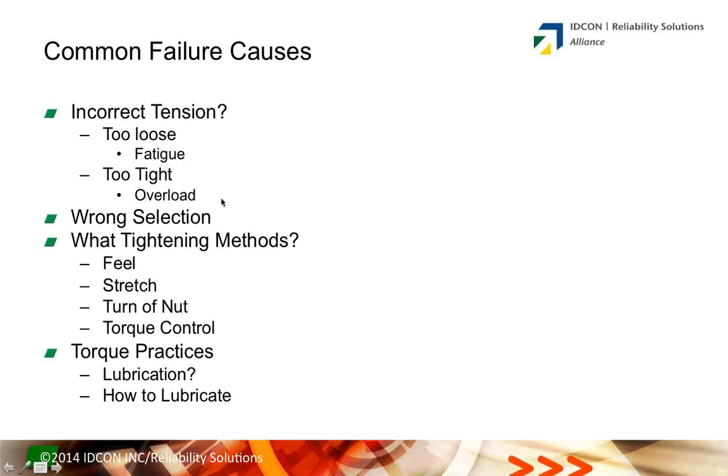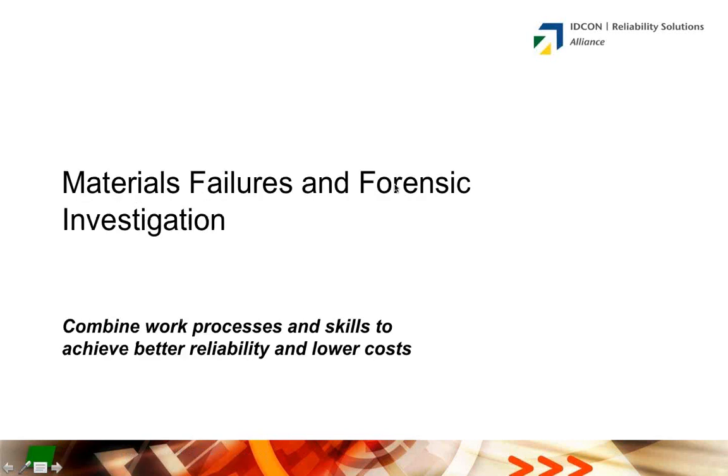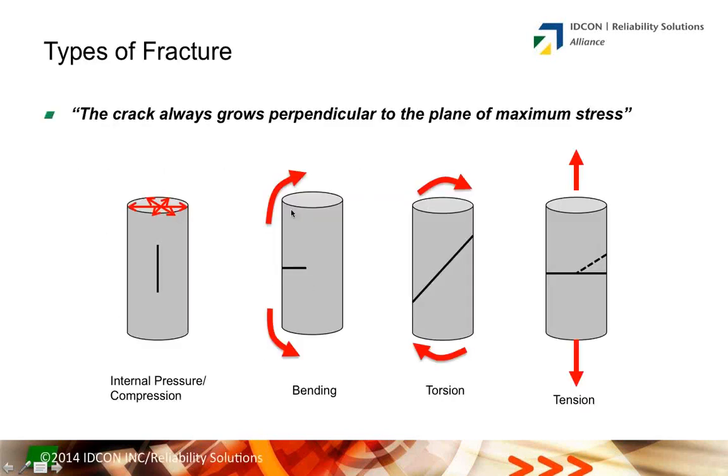So how do I tell the difference between a fatigue failure and an overload failure? First of all, when I'm looking at fractures and fracture faces, rule number one, the crack will always grow perpendicular to the plane of maximum stress.